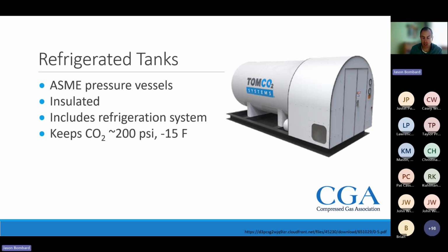One difference between these and the other tanks for cryogenics is that typically you won't have an issue with the relief valve opening on these, because the refrigeration system is condensing whatever vaporizes.